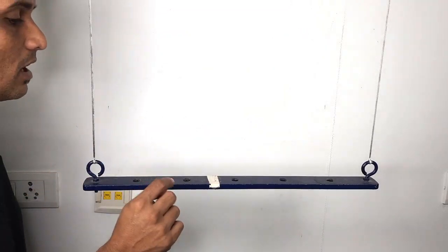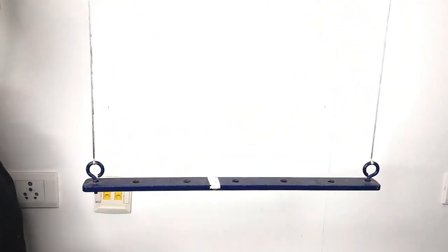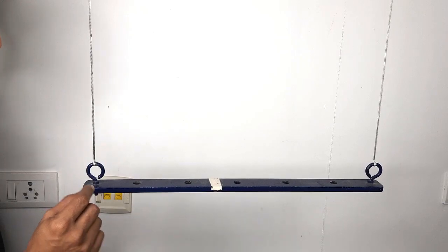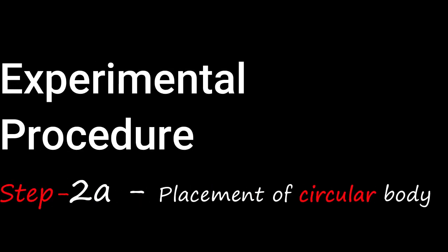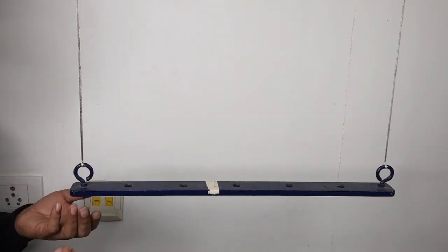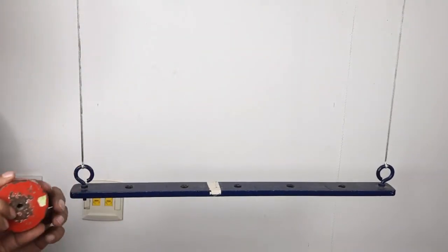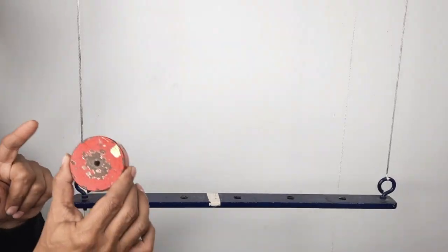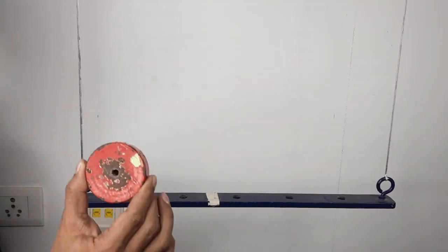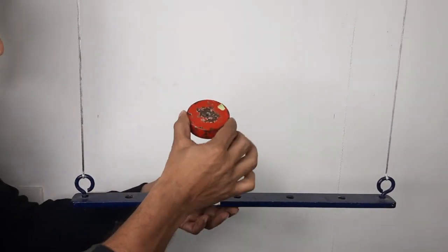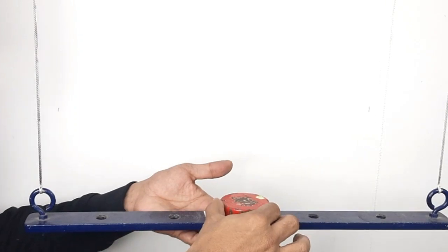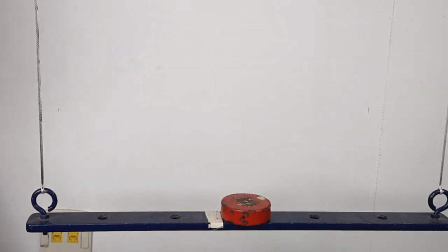As the mass of this bar is 1.6 kilogram, the moment of inertia will be just mk squared. After getting the K and the moment of inertia of this bar, I can use another system to find the moment of inertia. I know the mass of this body. I am going to superpose this body on my parent system and repeat the procedure.